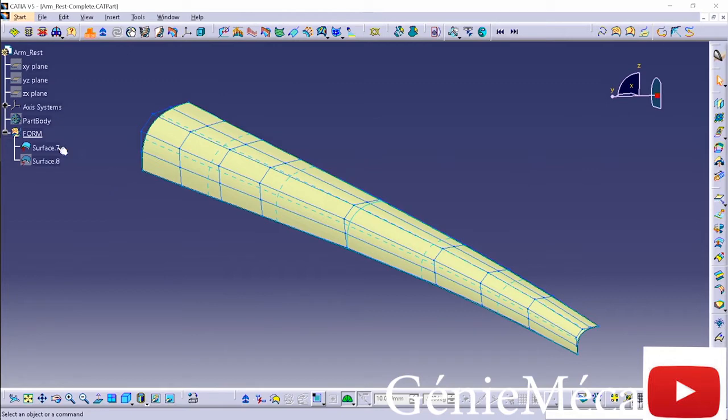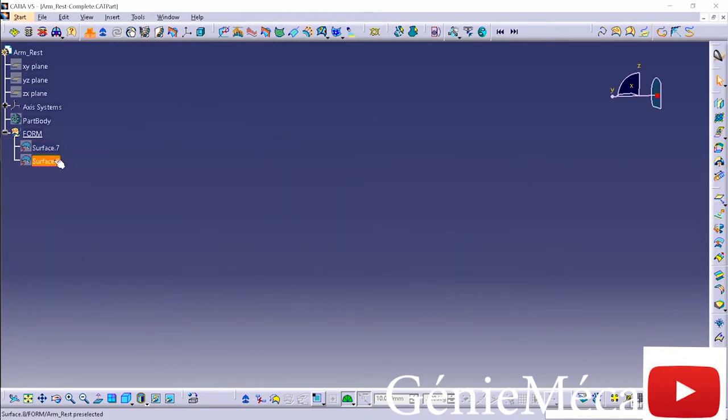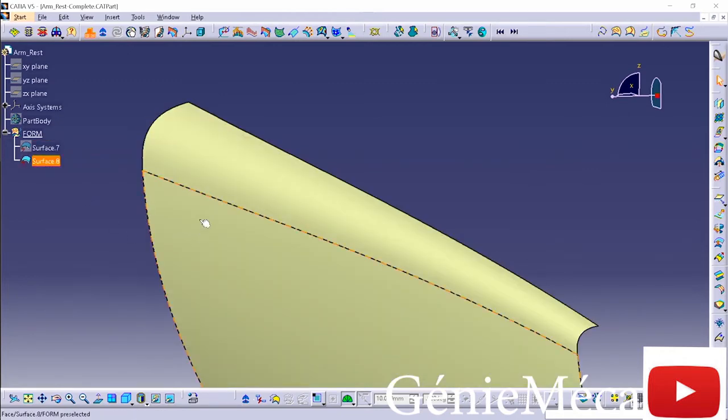Another example, let me hide this and show this. You'll see that I have this surface attached to this surface. These are wholly two independent surfaces that have been joined together across a boundary. This is a splitting or a facing tool that trimmed back that surface and joined those two surfaces together.